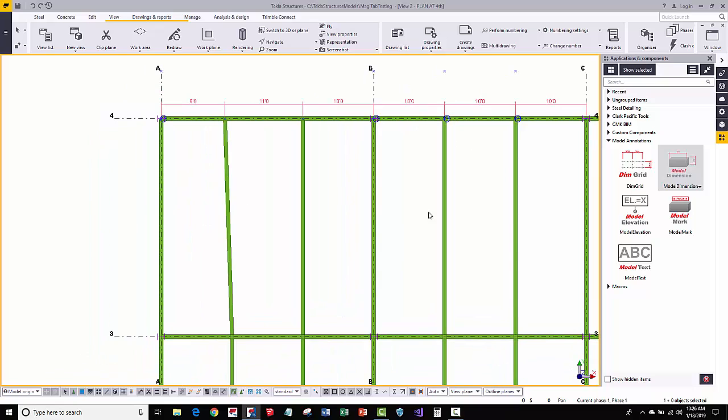Okay, so let's go ahead and do a Y dimension. So we'll just activate the command, and this time I'm going to pick the origin point, and then I'm going to pick the X direction in the Y global UCS, right? And then I'll pick here, because I want the text to be going upwards this way. And then I'm just going to simply pick, and I'm going to intentionally pick different dimensions here and different locations, and then middle mouse button.